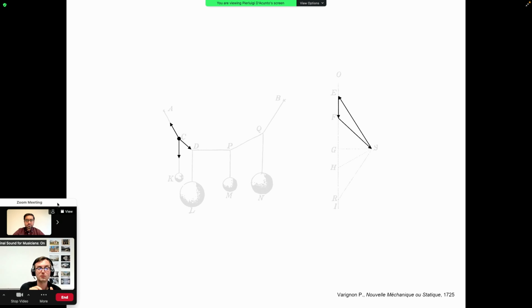These three forces can be combined in such a way that they close a polygon we see on the right. So this is the so-called force polygon. This is nothing else than the principle of vectorial addition. In order to have equilibrium, the three forces should cancel each other, and they cancel each other when they close